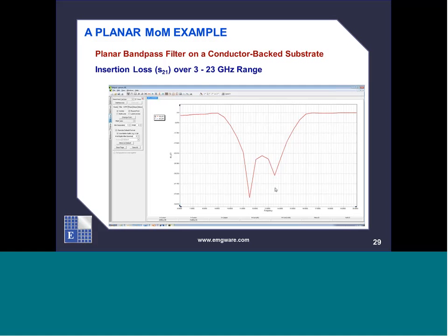So as you can see, if I want to do a bandpass filter, even though FDTD's computational domain is much bigger than method of moments, I would go with the FDTD because in one shot, I can get the entire frequency response, and you saw it was so smooth and nice because you got an FFT of the time domain information right there. But in frequency domain techniques, I have to run at each frequency and maybe use some sort of interpolation or adaptive frequency sweep or different types of techniques. But still, I have to repeat it. So there's no free lunch. You can use a time domain. It's bigger in terms of computational cost, but you get a better response at the end.